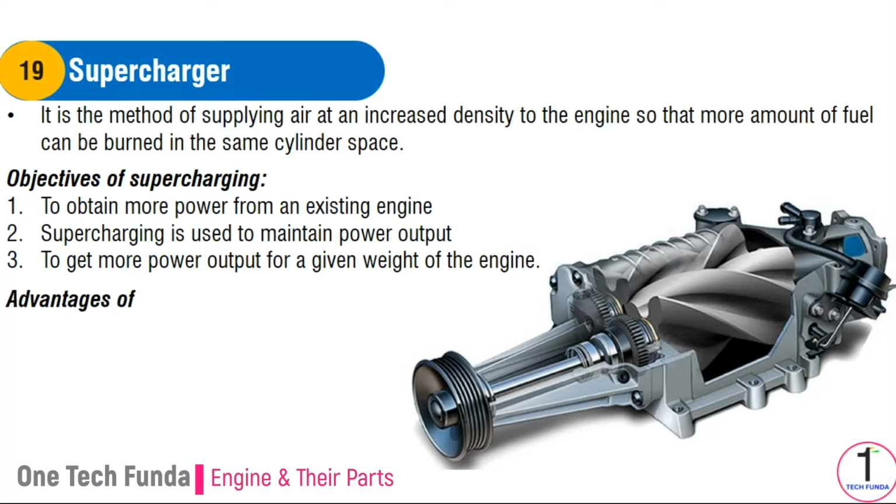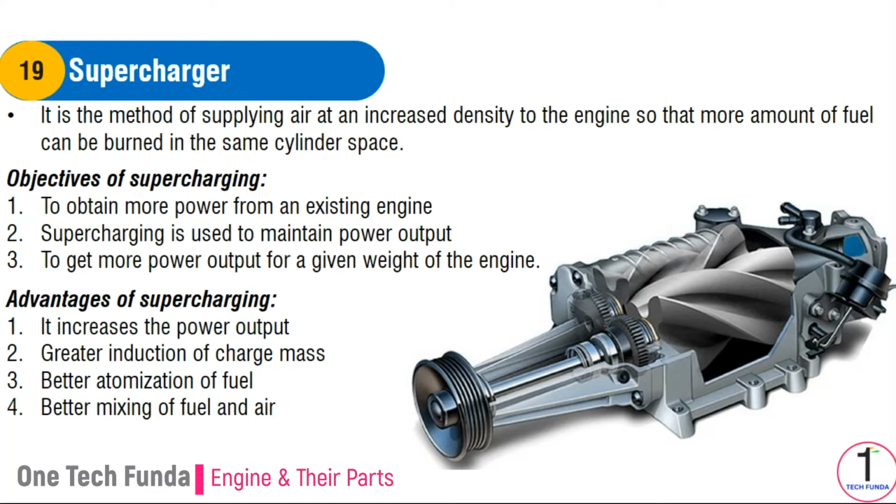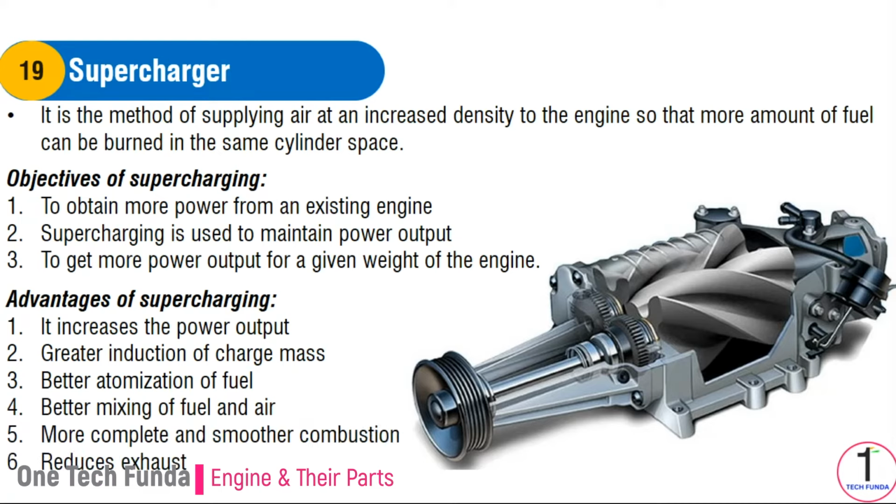Advantages of supercharging. The following are the advantages of supercharging. It increases the power output. Greater induction of charge mass. Better atomization of fuel. Better mixing of fuel and air. More complete and smoother combustion. Reduces exhaust smoke and increases overall efficiency.